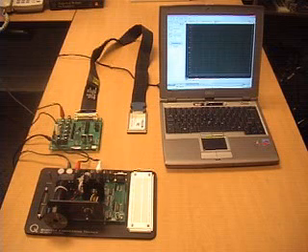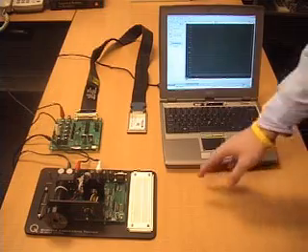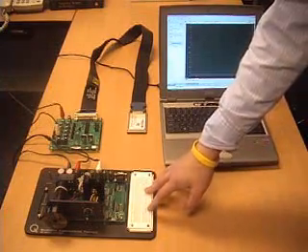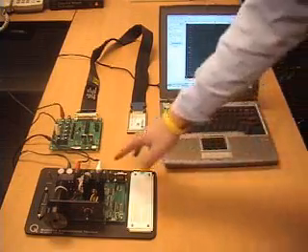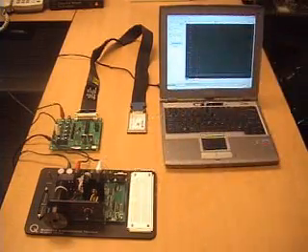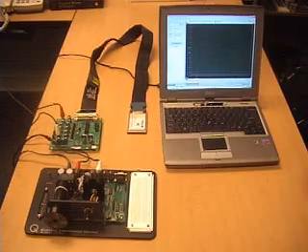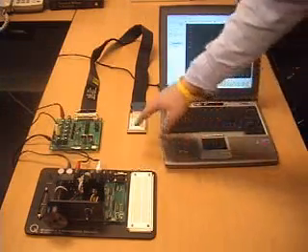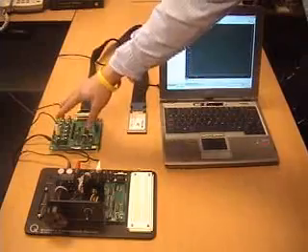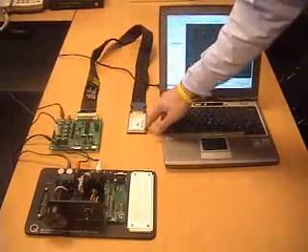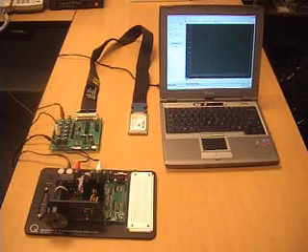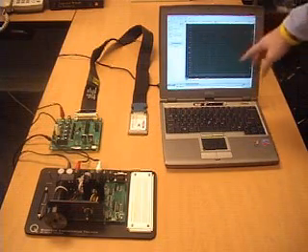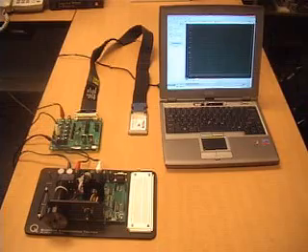Components of the system that we're using here today are the DC motor from Quanser, and essentially I have two signals coming in and out of this DC motor. I've got one which is my command signal, an analog voltage, and then I have a tachometer, also another analog output voltage, and I'm going to interface those to my PC through this interface board, which essentially just breaks out all of the lines available here on my National Instruments data acquisition board. So I'll plug that into my laptop and then be commanding and driving all of that from my software here